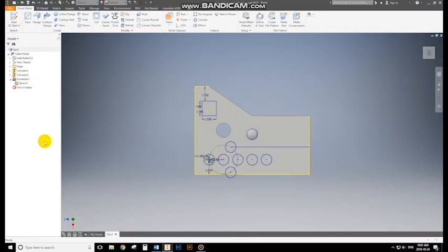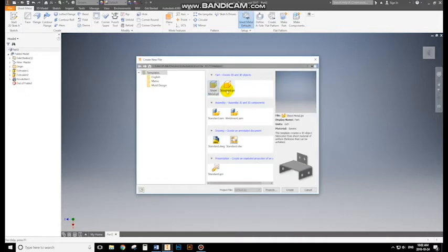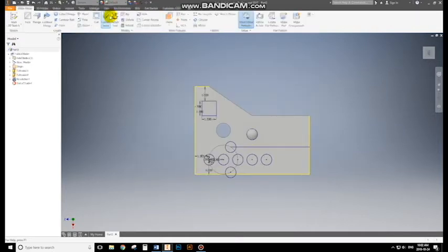In First Robotics Competition, a lot of the parts we will be making will be made out of sheet metal. Autodesk Inventor has special tools to help make sheet metal parts that we can use if we set our part as a sheet metal part. We can do this by either selecting sheet metal part right when we create a new part, or by selecting Convert to Sheet Metal in the Environments tab.